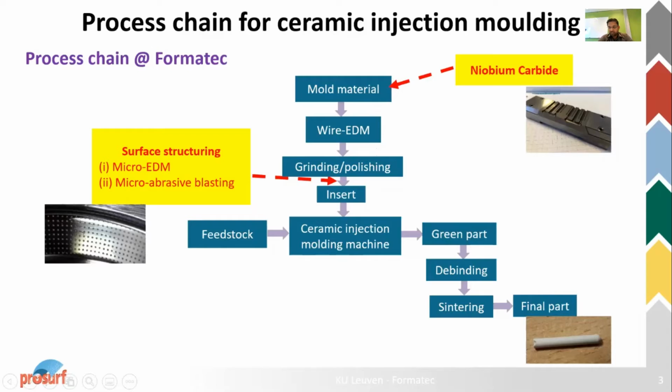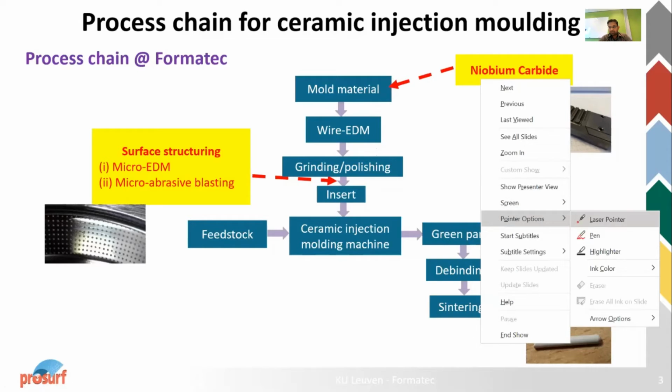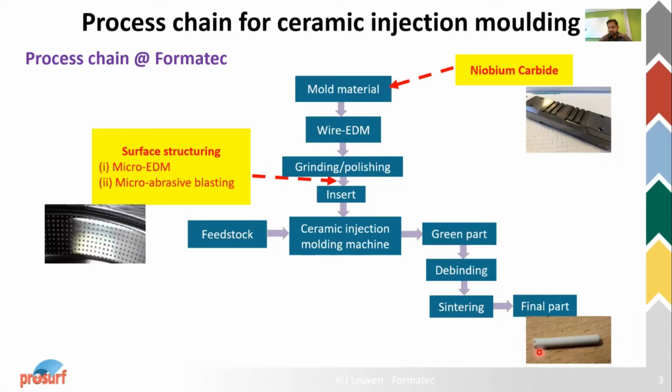As you can see here, this is a 3 millimeter ceramic cap, which was the main demonstrator in this ProSurf project. This ceramic cap is made from POM binder with some zirconia particles, and it finds application in high temperature sensors.